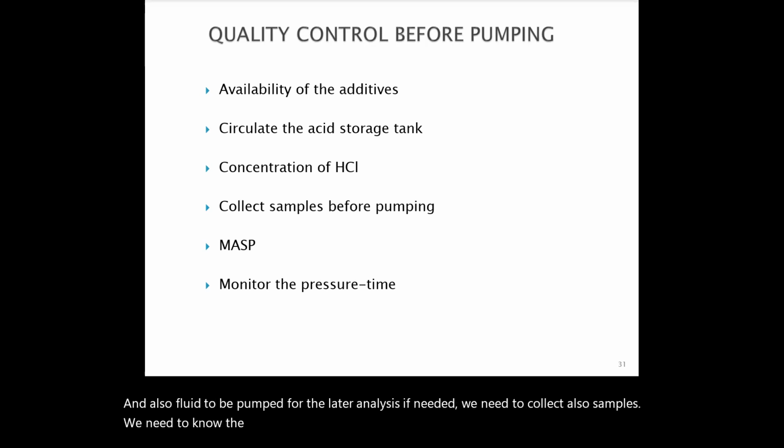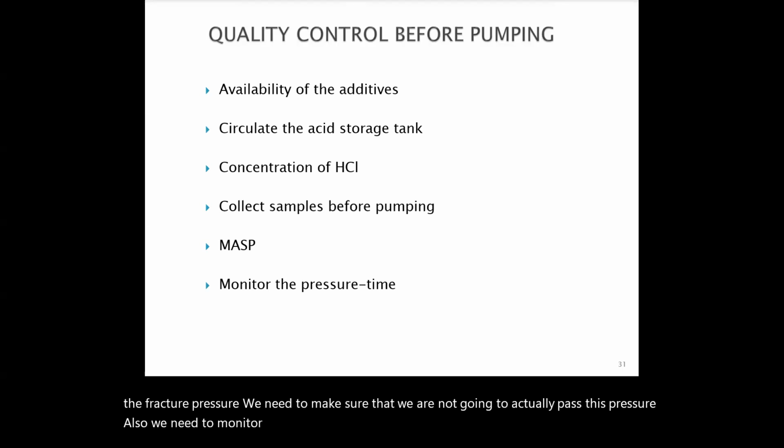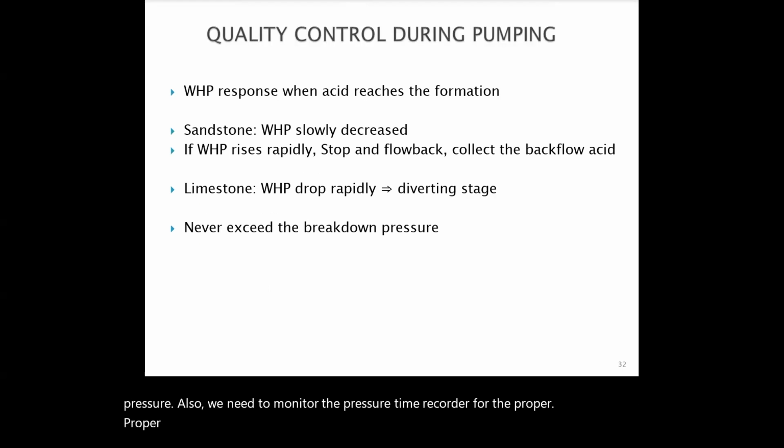The maximum anticipated surface pressure is very important, based on the fracture pressure. We need to make sure that we are not going to exceed this pressure. Also, we need to monitor the pressure time recorder for proper operation.